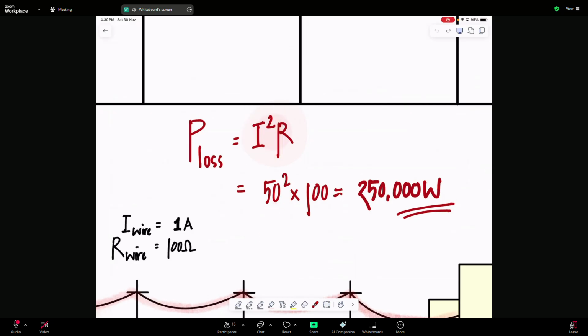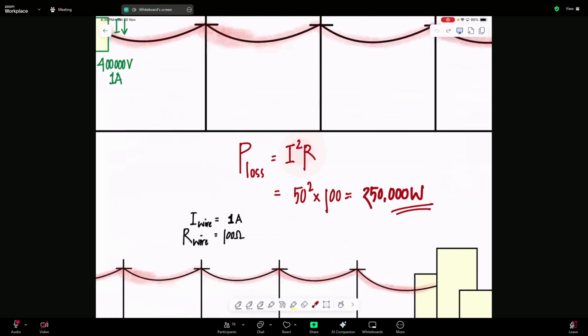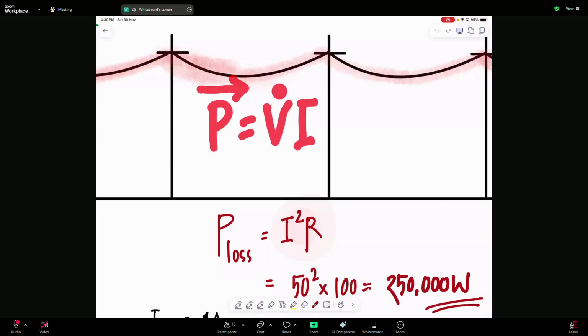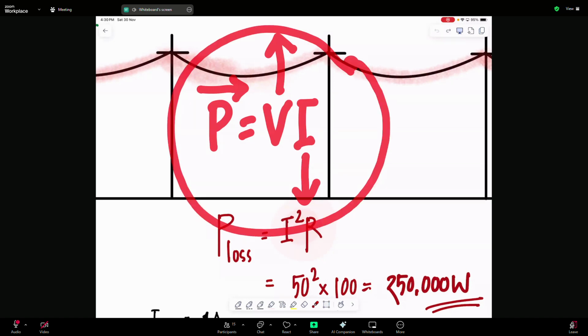So they found only if there was a magical way that we can reduce current. And the first thing students will say is increase resistance, right? But then again, you're increasing resistance. What are you doing again? Power loss. So the hypothetical thing that we came up with was that if only there was a way that I can keep my watt, same power, and I could increase the voltage that I'm transmitting so that current becomes what? Less. That was the ideal scenario.